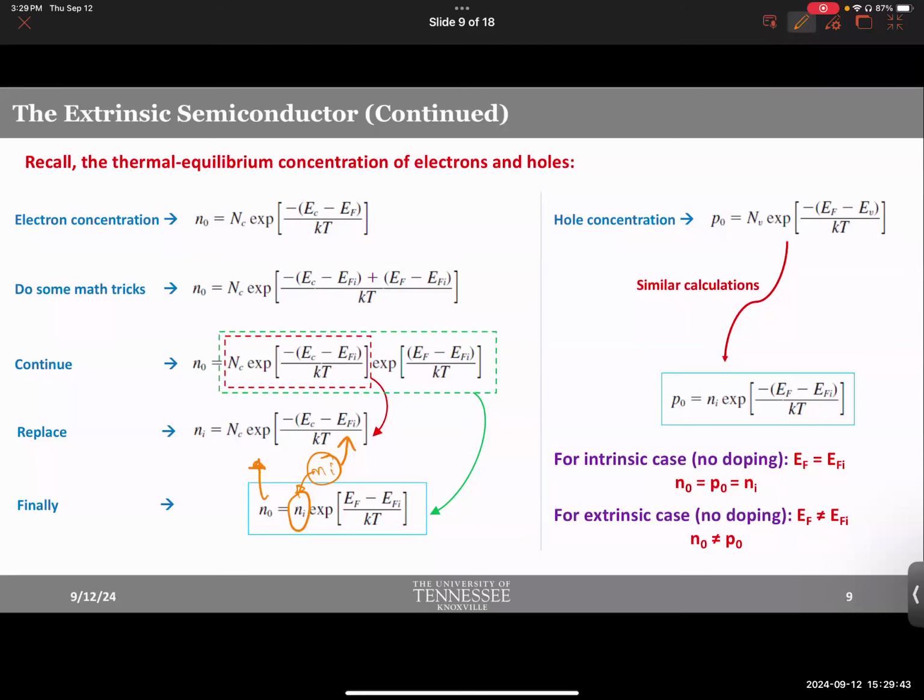Notice that? So there is a need to choose a material that has a higher intrinsic carrier concentration to make more carriers. But if a material has a really, really low carrier concentration to begin with, no matter what you do with Fermi levels, you can only do so much, because this will kill you, right? This intrinsic carrier concentration will diminish the effect of Fermi level engineering.